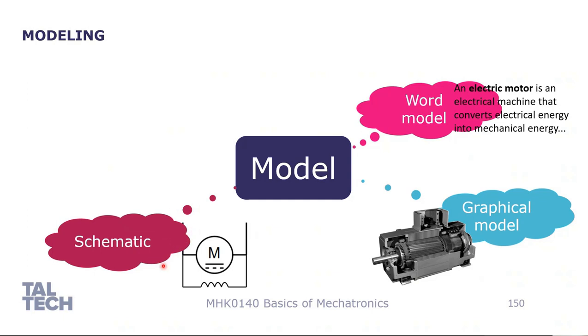Here we have the shunt DC machine. We have the armature winding shown with a bold line. We have the excitation winding connected in parallel, the shunt winding. We know why it's needed. The excitation winding produces magnetic flux, and if there is a current in the armature winding, we are getting movement, so our machine starts to rotate.